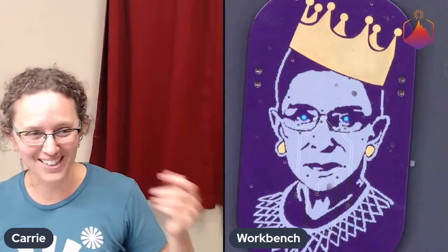There are vias there, and what you're seeing are the holes basically in the vias. And so what I can do is make those holes a lot smaller so that the silkscreen and solder mask will completely cover them, and they will basically be invisible. So that is something I will be improving upon on the next revision.